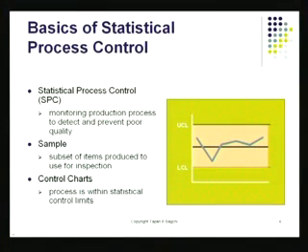We apply the same principle when we do statistical monitoring. So if you go back here, you'll notice that the chart that I have here has two quantities. I've got the upper control limit, UCL, and the lower control limit, called LCL. These control limits basically show the limits of natural variation of the process.